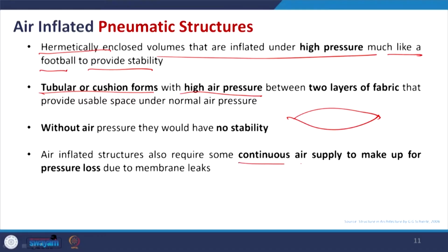Where air is kept locked between two layers. Okay. And now, without air pressure they would have no stability, that already I have explained with this, where I can just crush it like this. The air inflated structure also requires some continuous air supply to maintain the stability. It is the same, during that particular process, there will be slow leakages. So, in order to maintain that, we have to put in air, not maybe regularly, even like I can give you the example of the cycle tube.